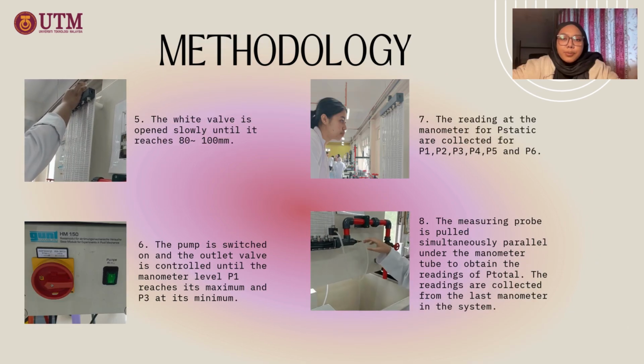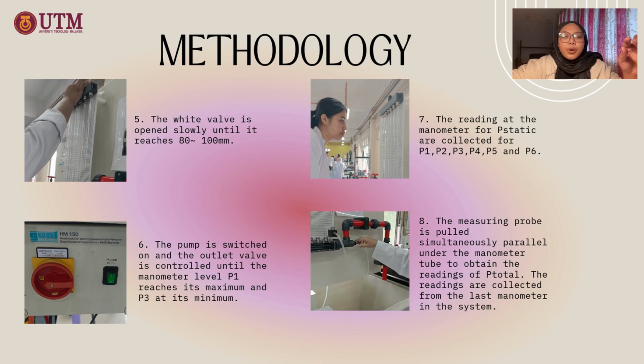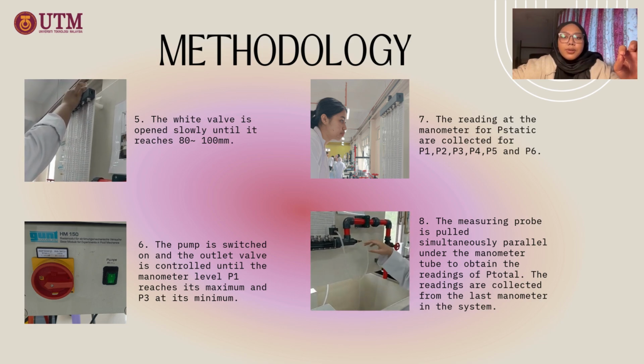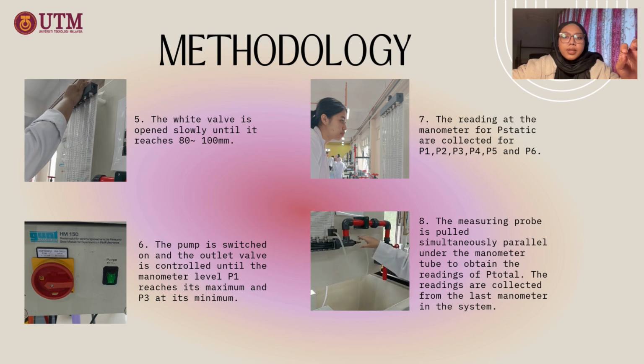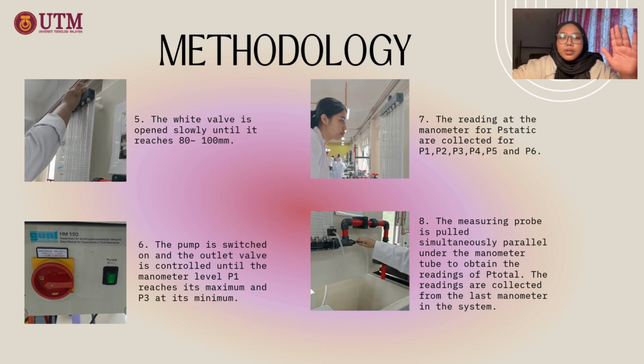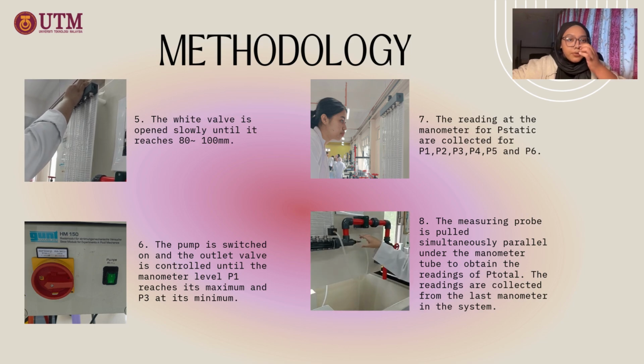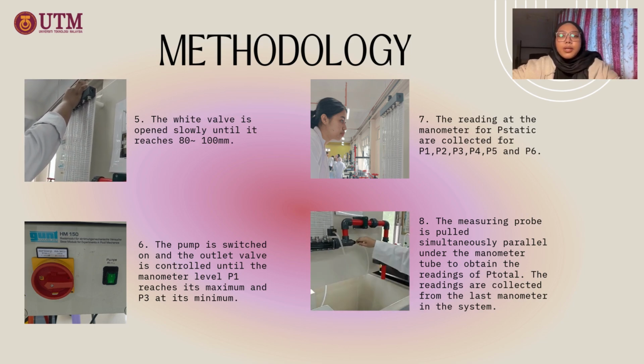And then the white valve is opened slowly until it reaches 80 to 100 millimeter, and the pump is switched on and the outlet valve is controlled until the manometer level P1 reaches its maximum and P3 reaches its minimum. The reading at the manometer for P static are collected for all the data, which is P1, P2, P3,